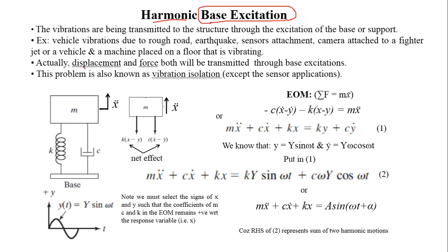What is going to happen is that displacement and force both will be transmitted through base excitation. When the base or the support of an apparatus or an equipment is in vibration, it is going to transmit both quantities, displacement and force. We should know the magnitude of force that is being transmitted to the device and the magnitude of displacement that is being transmitted. Both magnitudes are important for us as vibration engineers. In this topic we are going to explore the dynamics of this behavior, and find the expressions by which we can know the amplitudes of the displacement being transferred, and the amplitudes of the forces being transferred.